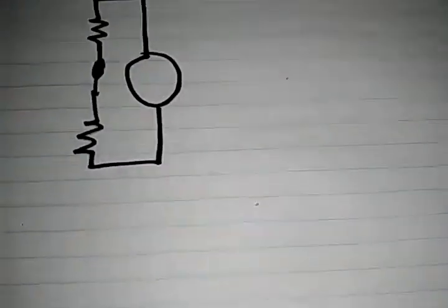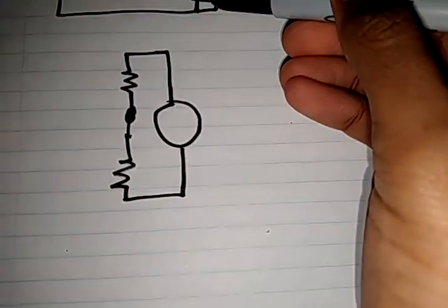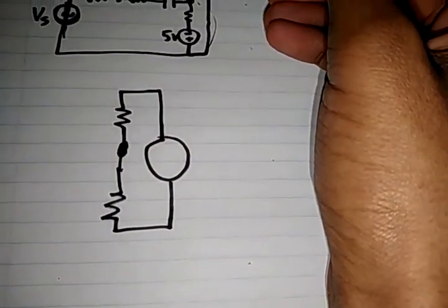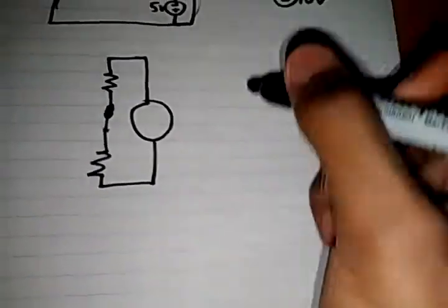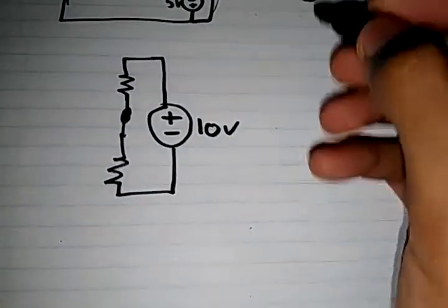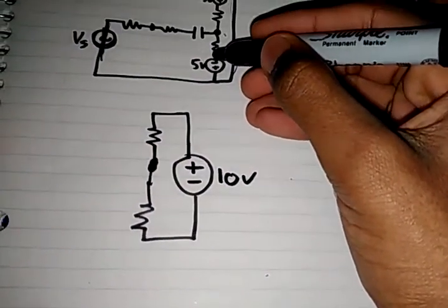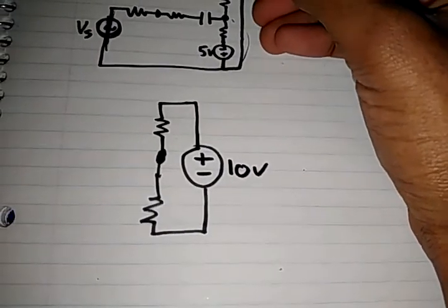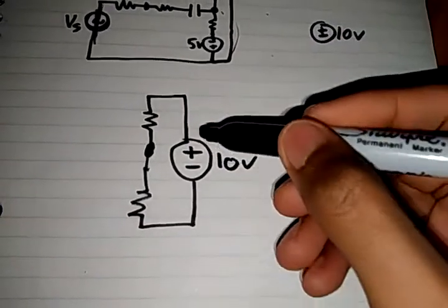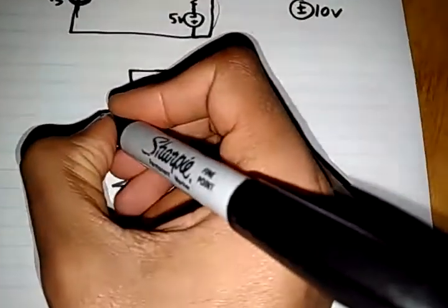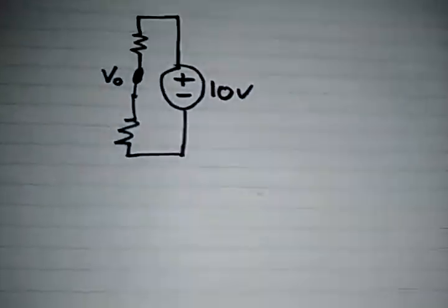Something like this. This is a plus 5 volts going out here. It's hitting a minus 5 volts and is bumping up again 5 volts. So in other words, I'm pumping up 10 volts in total. Because if I assume this is ground, then this is 5 volts coming out and then bumping up again 5 more volts, which I can simply write as 10 volts pumping up. This is the node, which will give us our VO, plus, which is connected to ground.